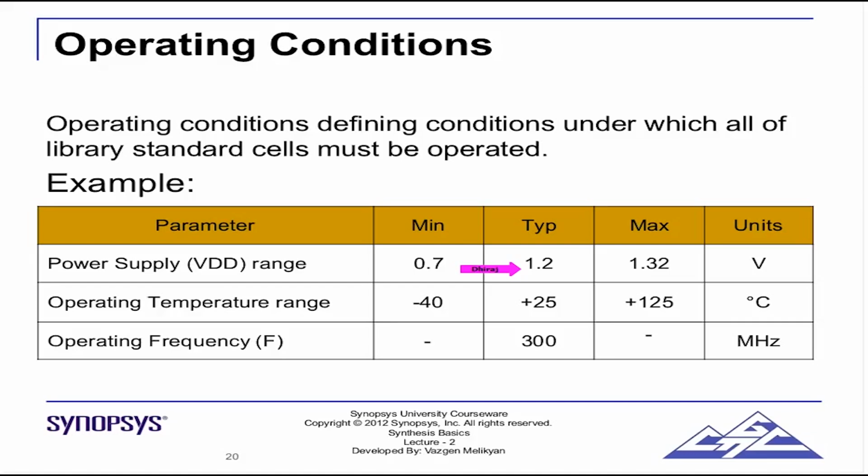So we define that the chip should work at minus 10%, plus it should work for a slow process. Also, it should work at higher temperatures. So now we have three things: P, V, and T.